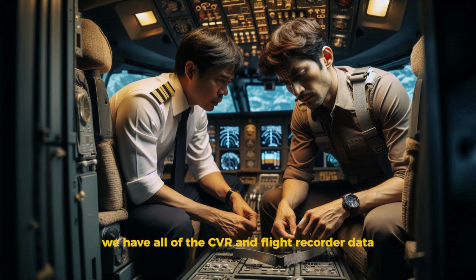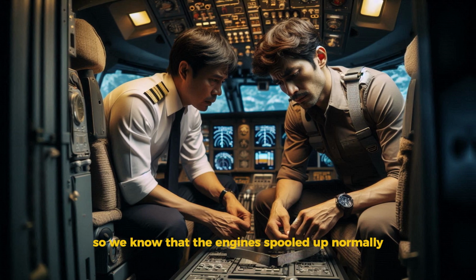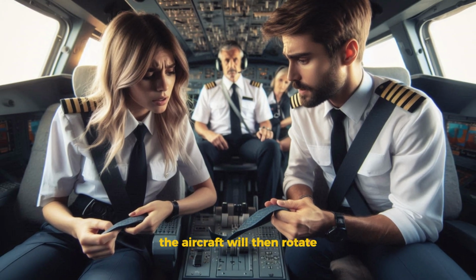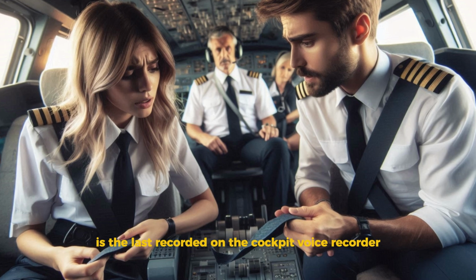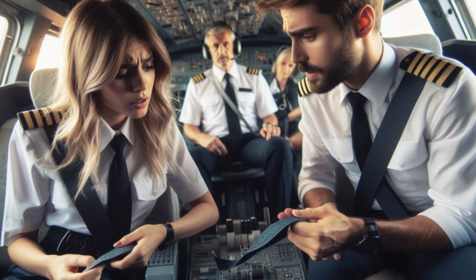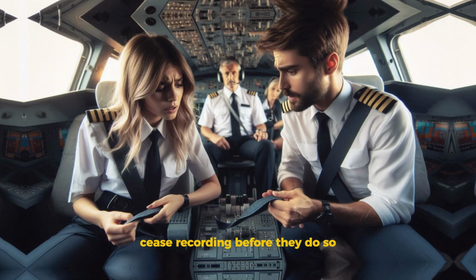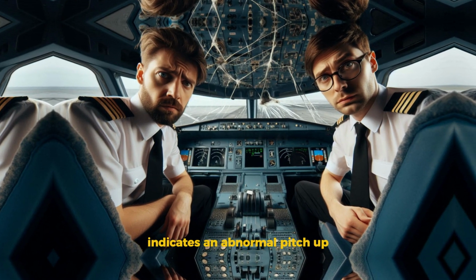We have all of the CVR and flight recorder data up to this point, so we know that the engines spooled up normally and that the aircraft accelerated properly, just as it had on the previous flight out of Camp Bastion. The aircraft will then rotate. The first officer requesting gear up is the last recorded on the cockpit voice recorder. Approximately 2 seconds later, all recordings are lost. The flight data recorder and the cockpit voice recorder cease recording. Before they do so, the final 2 to 3 seconds of the aircraft's takeoff indicates an abnormal pitch-up.